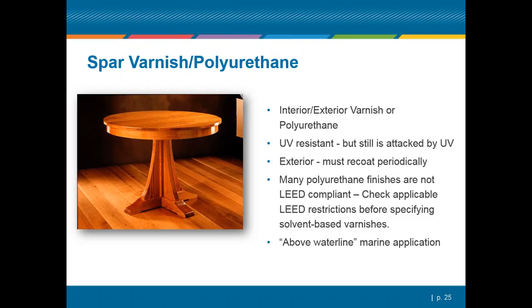If there is any way that these doors can be set back so that they have some shading and don't take full sun all day long, that would be more desirable than putting them out where they catch full sunlight at all times. They do become a maintenance issue, and recoating those exterior finishes becomes necessary over a period of time, every couple, 3 years maybe, depending upon what kind of sunlight they get exposed to. Many of these polyurethane finishes, as we said before, are not LEED compliant, so we need to make sure we're checking proper codes. And anything exteriorly with a wood finish, just keep in mind it's a maintenance issue.